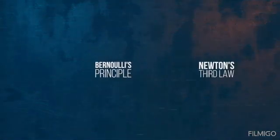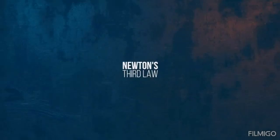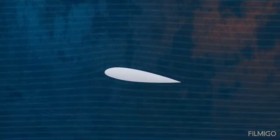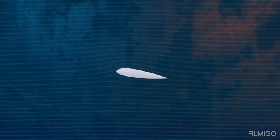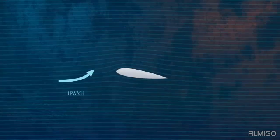What about the explanations of lift that are based on Newton's third law? These don't consider the velocity above and below the airfoil, but instead look more generally at the behavior of the fluid. If we look at a wider area, we can observe that the effect of an airfoil can be felt far beyond its immediate vicinity. Upstream of the airfoil, the flow is being swept upwards, which is called upwash, and downstream the flow is deflected downwards, which is called downwash.